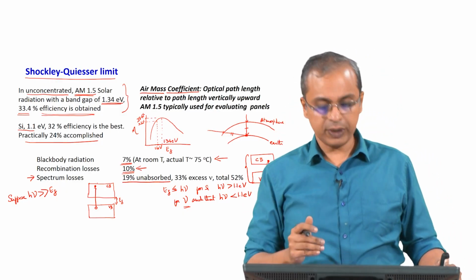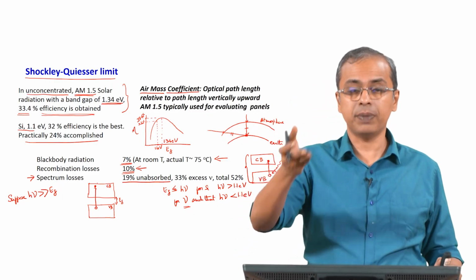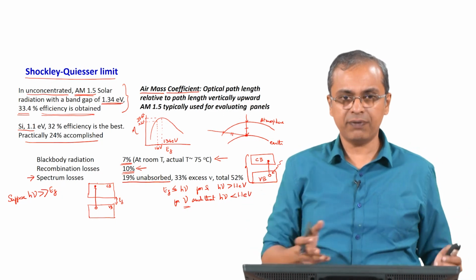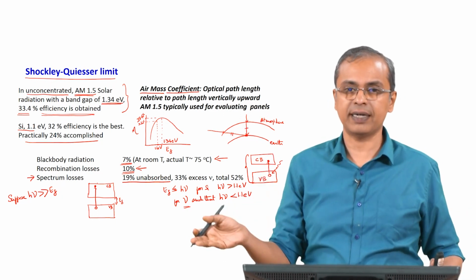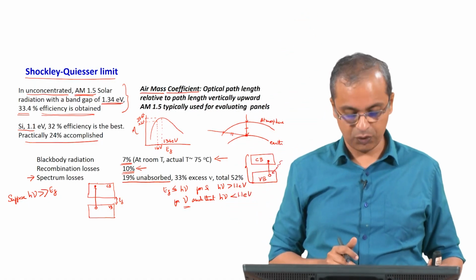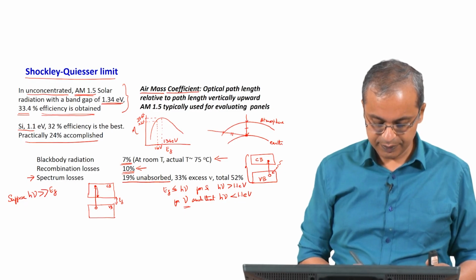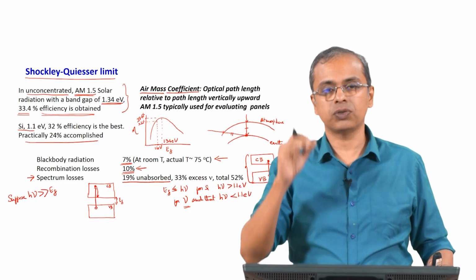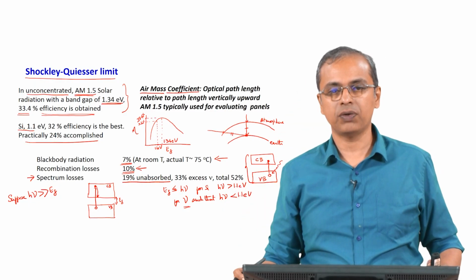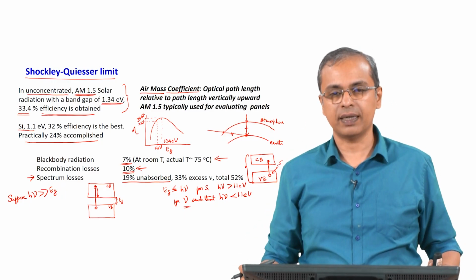Normally once you do that, that is not going to be a stable situation because there are a lot of energy levels below this position which are all sitting vacant, because that is by definition how the conduction band has been set up, most of it is sitting vacant. So, you have pushed an electron very high up because you had that much energy available in the incoming photon. What normally happens is it will just come straight down to the bottom of that conduction band, and that is where it will eventually settle down.